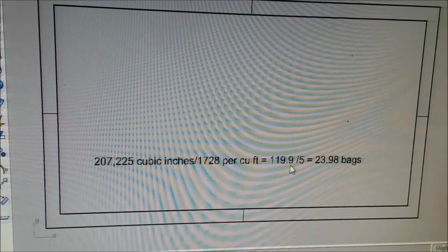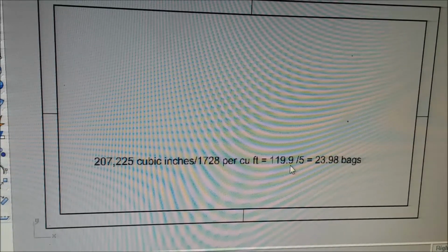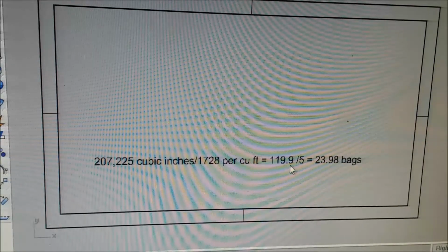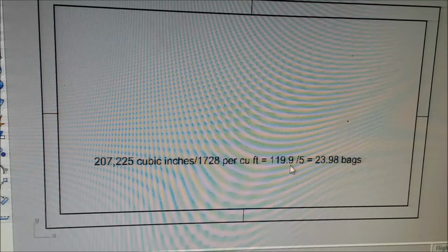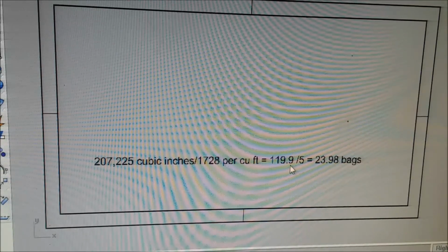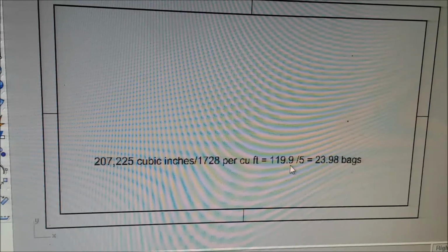We buy that sand because it mixes the 2 sizes of aggregate and the sand, and it fills up all the spaces between the rock really well. It's probably a superior piece of cement or concrete. When I first saw it, I said, "Oh crap! Look how much junk is in there." But when you take it in a jar and mix what you're going to make your mix out of, and sort of roll it around with a little bit of water in it, you'll notice that those pebbles disappear into the gravel, and it just makes it stronger. So it's not really a bad thing.